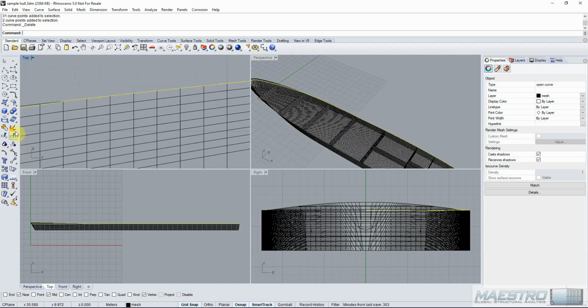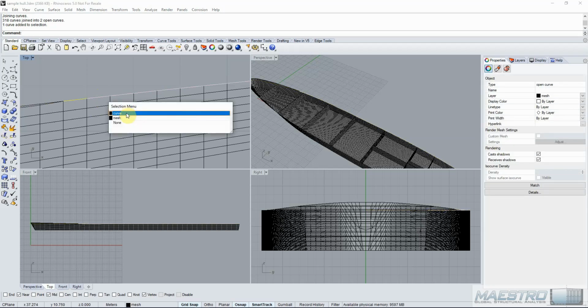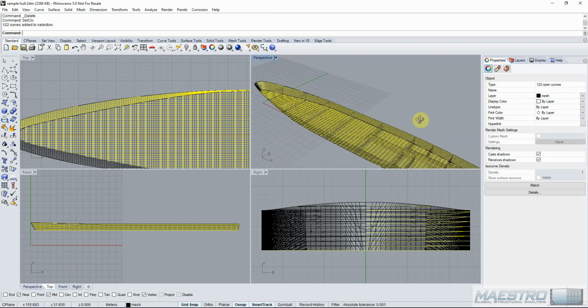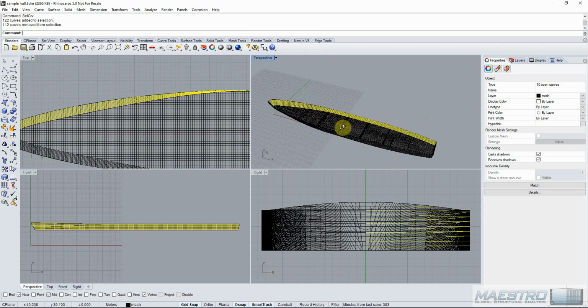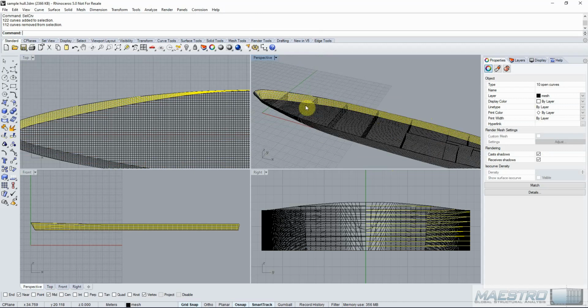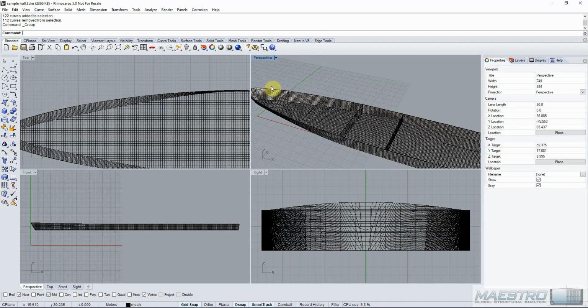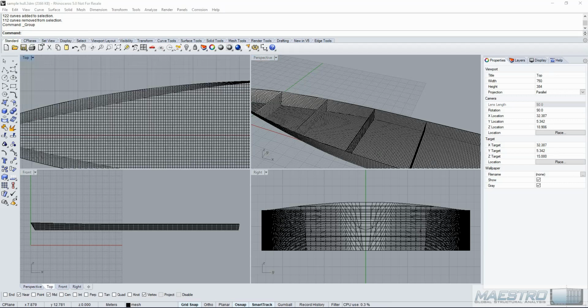So it might be easier to explode this one, deselect a segment, rejoin, and then delete those two curves. Now we'll deselect the curves on the hull, and we have all of our side shell stringers, so we'll create a group. Now that function would be the same on the opposite side, but for purposes of this demonstration, we'll just deal with the starboard side.